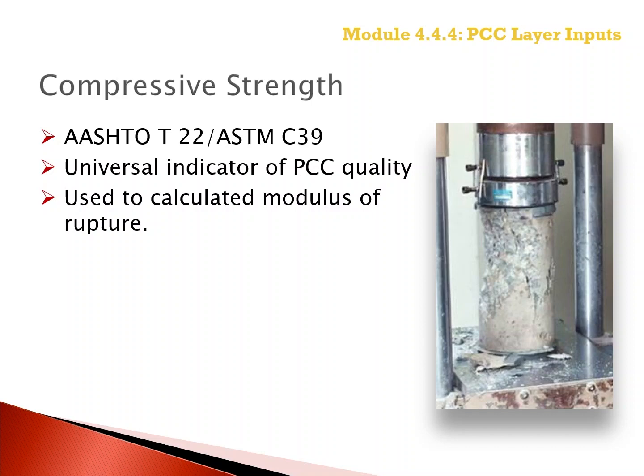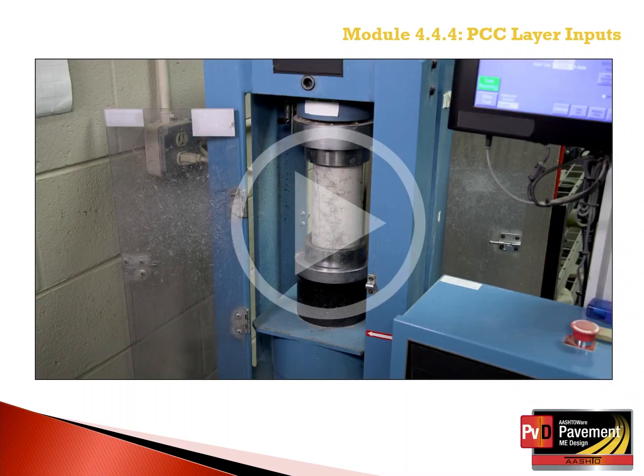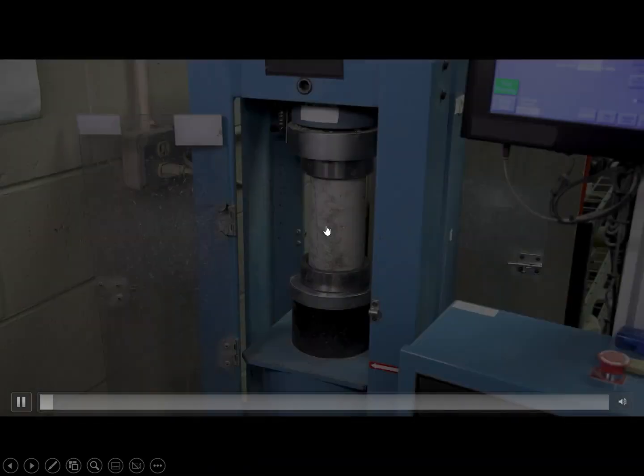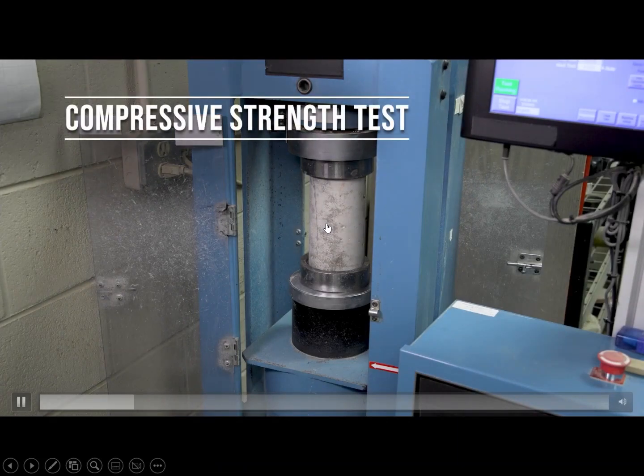This photo shows a PCC test specimen being loaded to failure to assess the unconfined compressive strength. The load rate has a significant effect on the strength and is specified in the test protocol. This slide includes a video clip of the compressive strength being measured in the laboratory in accordance with AASHTO T22.